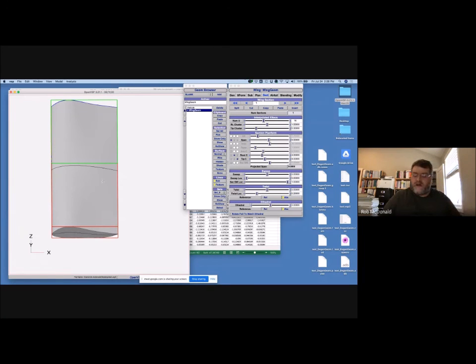And this can be done. What I'll tell you about doing this is it's very tricky. It's very sensitive, because you'll end up with an airplane that has a very narrow permissible CG range. Now, for a UAV, that may not matter, because let's say it's an electric UAV, so the batteries are always the same weight. You're not burning fuel as you go, and you're always flying it with the same payload.